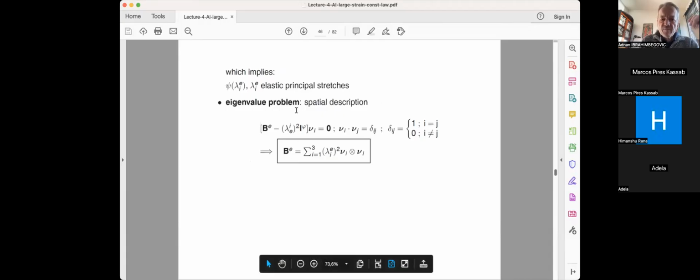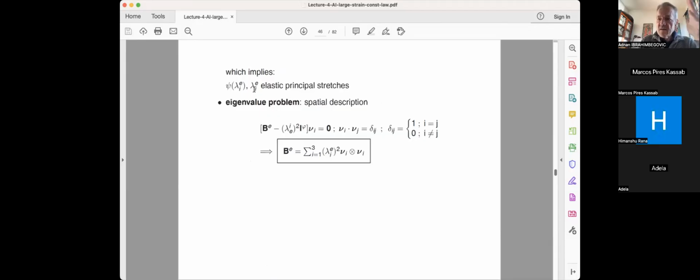Hence, you can then define all the strain energy to deal with that in terms of invariants. And in particular, we already advocated that instead of using invariants, we just take the elastic stretches, which I illustrated only for the 1D case, what that means. This is the ratio between the deformed length and the unloaded length, and make internal energy a function of these elastic stretches.